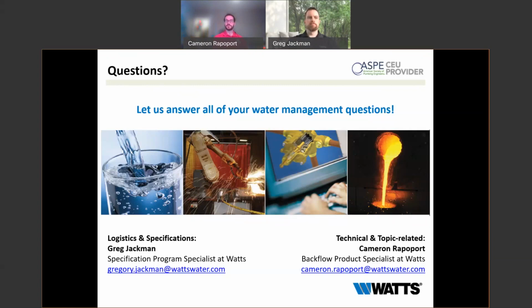So if you have anything other than a giant rock stuck in that first check, it'll likely close up the relief valve once you get a reasonable amount of flow anyway. So between those two things, one, code officials having made the decision on that trade-off, and it will probably happen pretty rarely, and two, the fact that if you get a lot of flow, it in most cases would close up that relief valve.